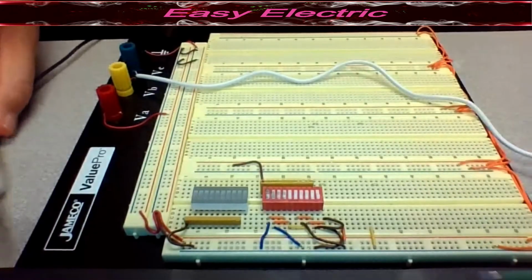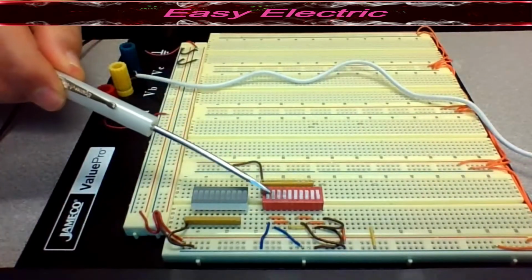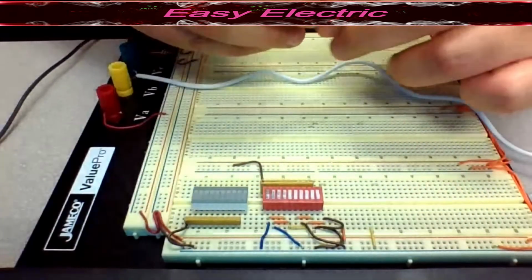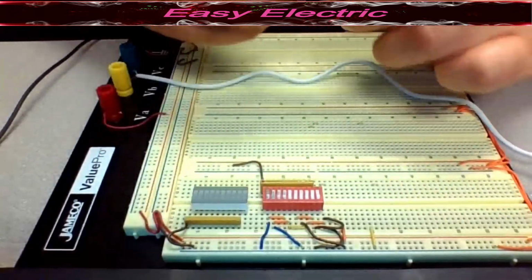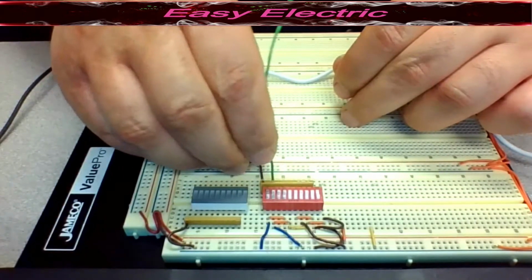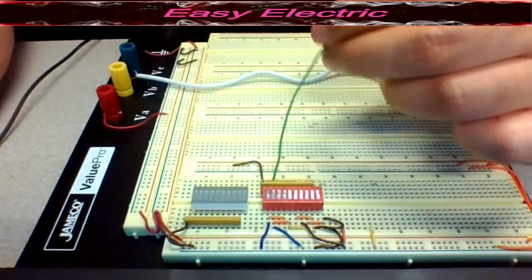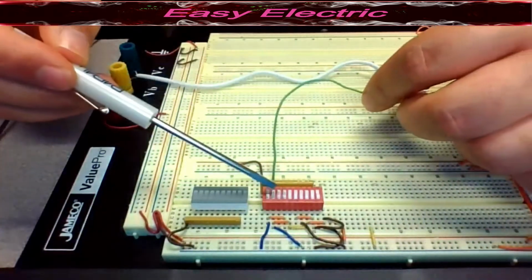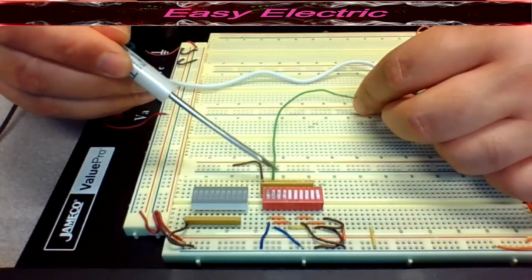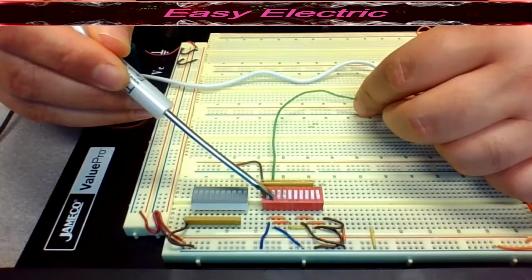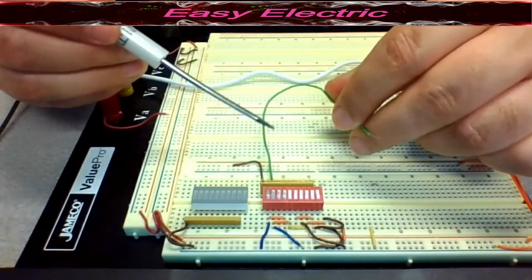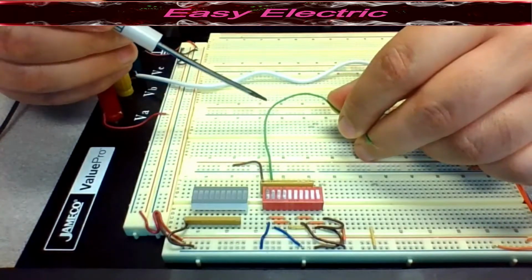For the input, we use the switch. You see, each of these switches is one input. If we connect a wire to each of these inputs, for example this one or the next one, we should be able to produce 0 or 1 with the corresponding switch. Here, for example, I connect this to the second switch. That means by turning it on and off, I'm able to make 0 or 5 volt here. I need this in the other lab experiments that we have.